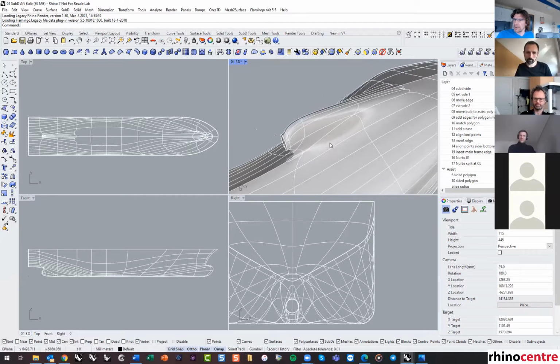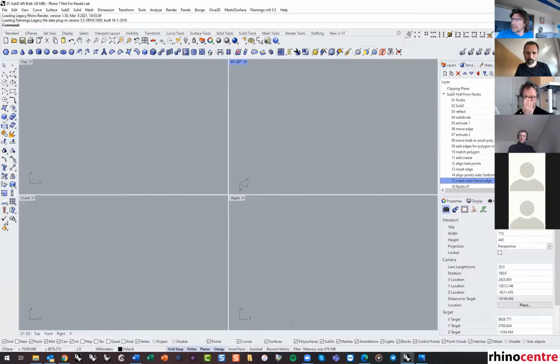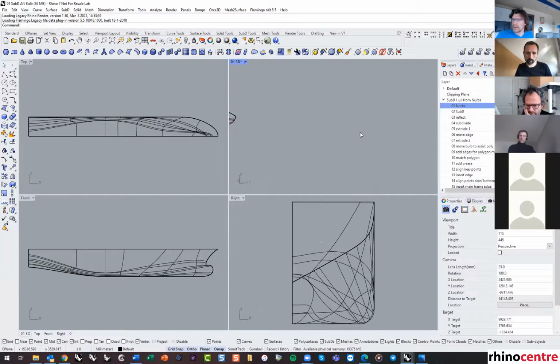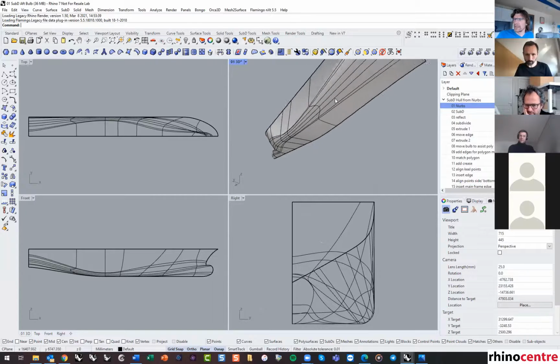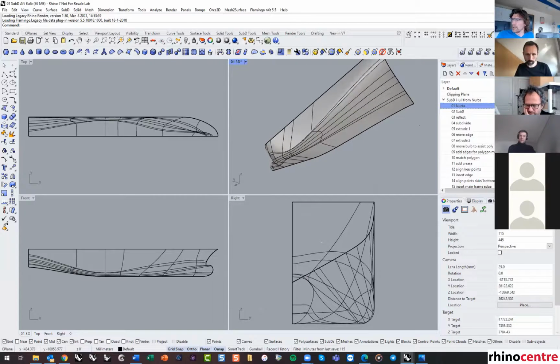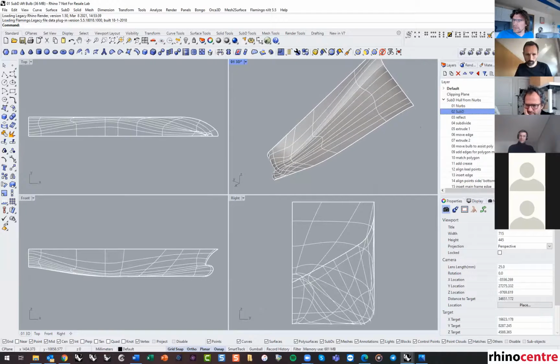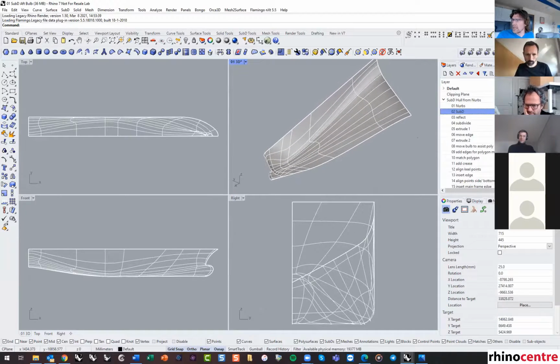And I can again show some of the steps on how to get here. I start with a pram type hull, and this doesn't contain this detail in the aft ship. So I convert it to a subdivision model, which shows more or less the same.